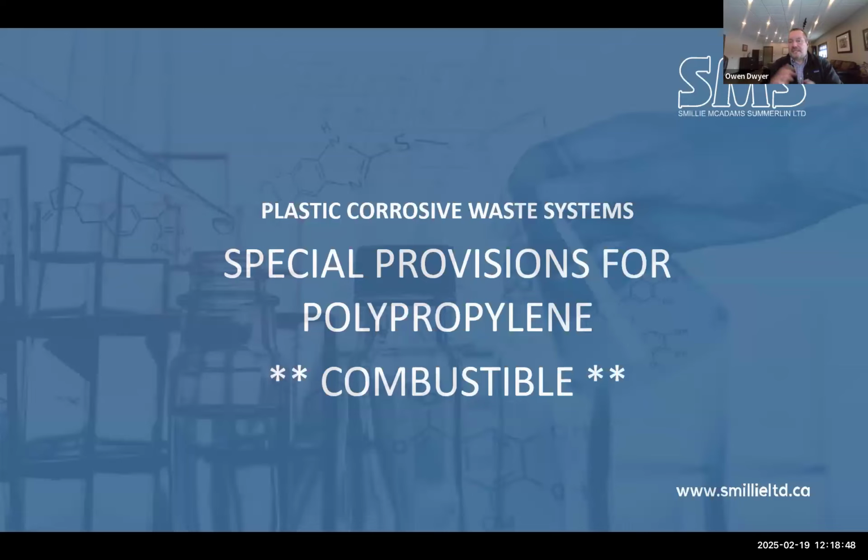So plastics, the CSA B181.3. Of the A, B, and C, I've covered the borosilicate glass and the duriron. This is the plastics options for corrosive waste here. All plastics, regardless of their flame and smoke, are classified as combustible. So they are in their own category with respect to fire stopping and limitations within the building space, like a plenum, for example. So that said, plastics are consumed in a fire.